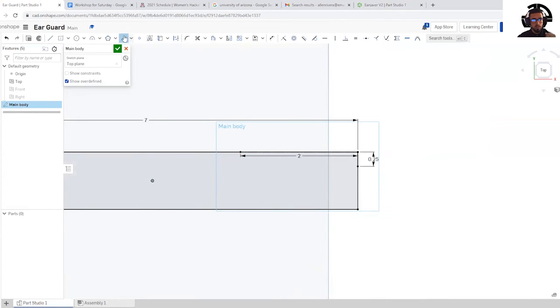I'm going to click on spline right here. There's multiple forms of splines, but right now I want to create a spline itself, not a spline point. We will not be reviewing that at the moment. So I'm going to click spline, and I am going to click on the first point after the 2 inches on this axis, on this x-axis. Okay, and then I'm going to click on the dot that I created on this axis and the y-axis. So I'm going to click both of them and it creates a spline.